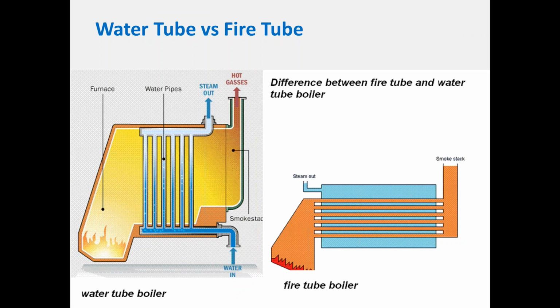And this slide here just really shows the difference. So we have a water tube boiler where there's the flame here, and then the water comes in as water at the bottom here, and as it rises up, it starts to form steam, and then there's a fraction of steam that comes out, and often the water gets recycled back down the downcomer. And then we have a fire tube boiler where the water is within the tank that's surrounding the tubes, and the flame or the heat flows through there.